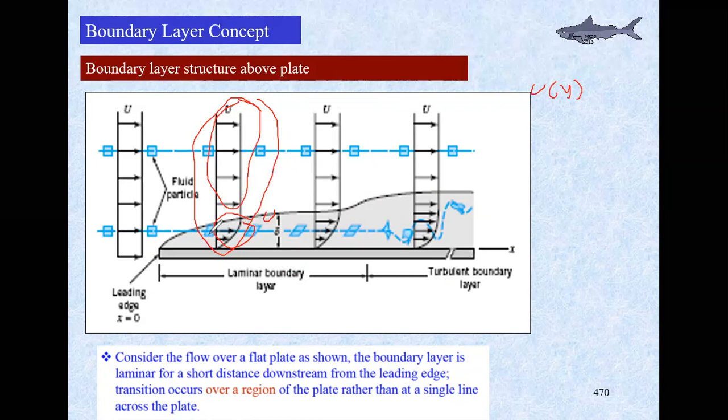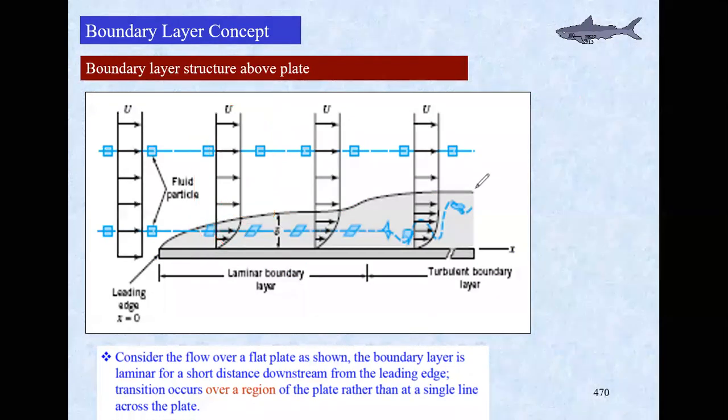So we scrutinize and get into detail on this boundary layer, which is actually fairly small, on the order of a couple of millimeters, for example. It's really small, but the boundary layer is really important to get the friction and the drag, the lift and the drag also.